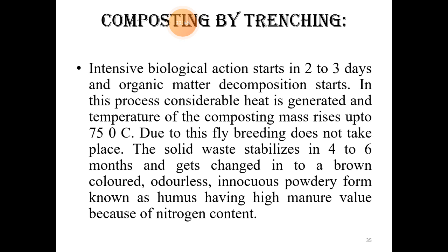The setup of these trenches is left for about 2 to 3 days, during which the organic matter gets decomposed with the help of microorganisms. During the process of natural decomposition, heat is generated that reaches a temperature of 75 degrees centigrade. This temperature generally stops the breeding of vector flies. The complete setup is left undisturbed for about 4 to 6 months.